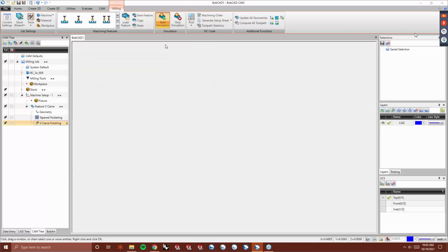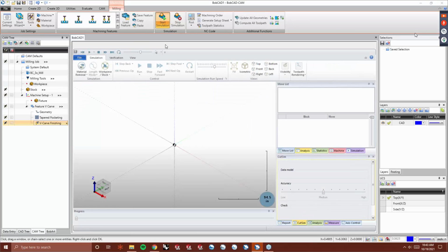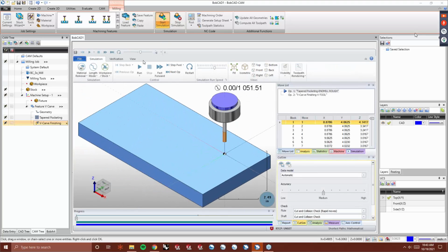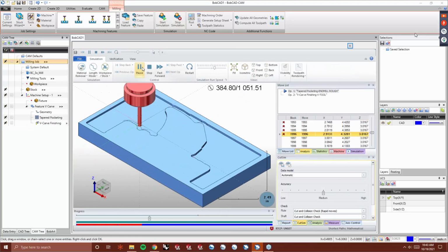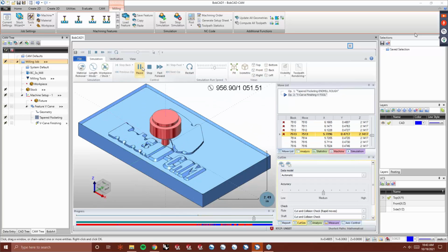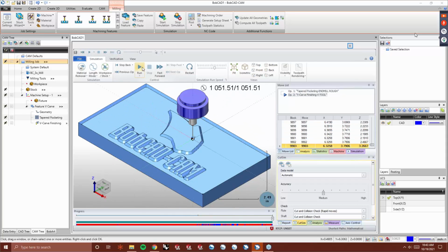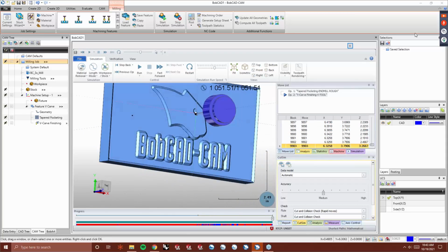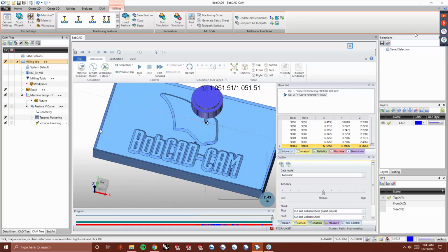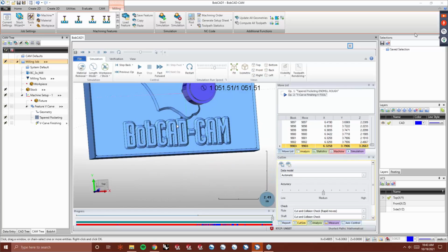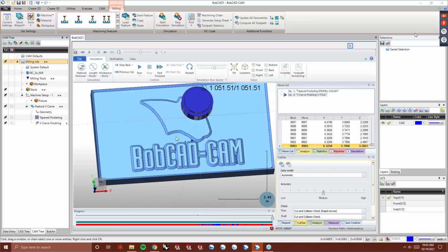Now it's going to offset that flat end mill for the tapered walls. So you don't do any additional pocketing, you don't do anything special. The only downside is you can't do an open pocket. So if any of you guys have wanted to do something like this, but you wanted to leave the walls, what you do is you define it slightly bigger and then just cut that down, or it be off the part, if your part's actually a little smaller than that. You just define your area that you're cutting a little larger.